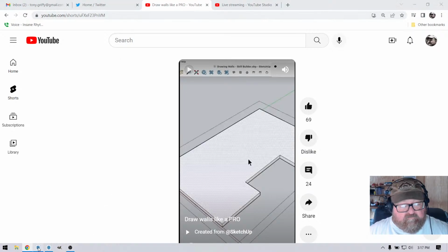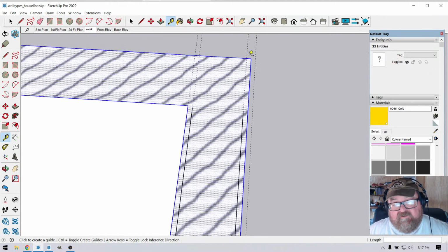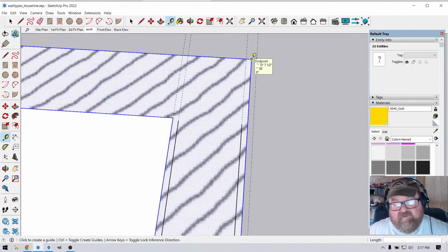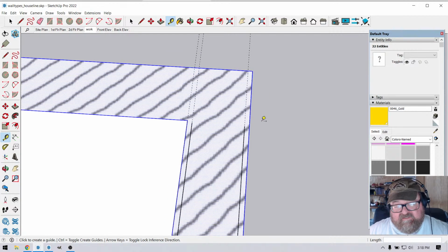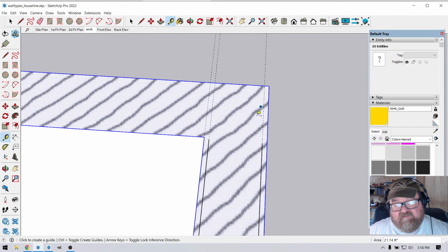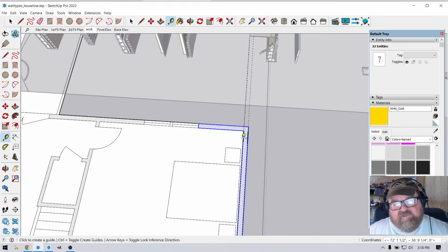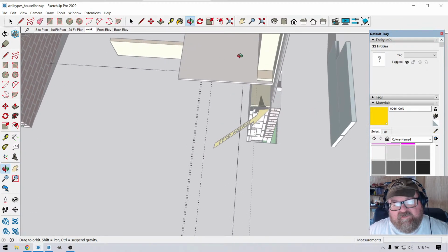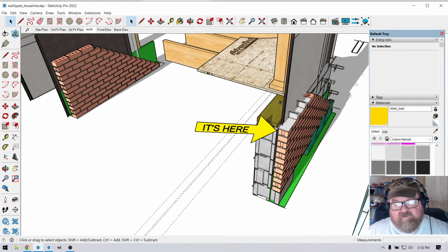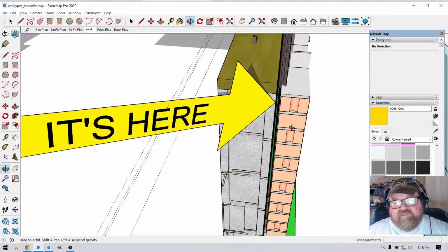But going back to this, it means that your house line, you would be indicating it here, and then you would have your OSB sticking out, and then you would have your siding sticking out past that. When in reality, your OSB, your sheeting, is flush with the house line. Right. And this goes back to placement, right? It goes back to sequence, really, because what do you do next after you lay your concrete block? You put this plate on, this mud seal, this rat seal.